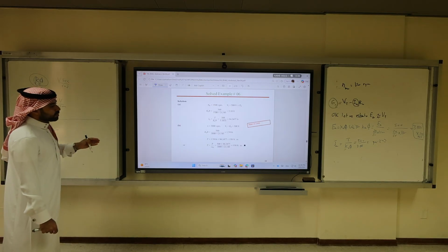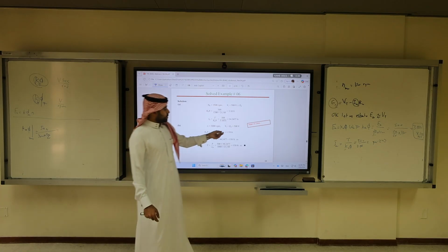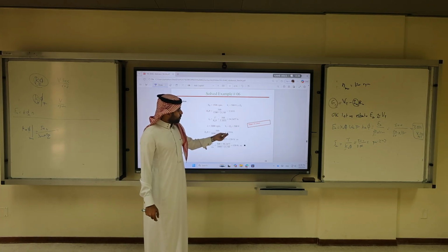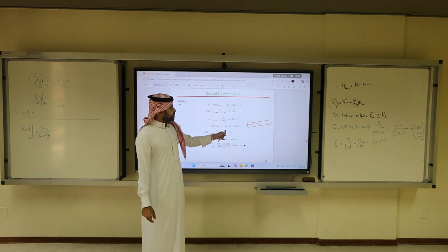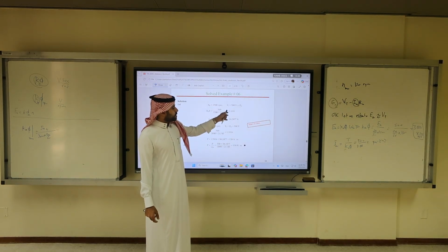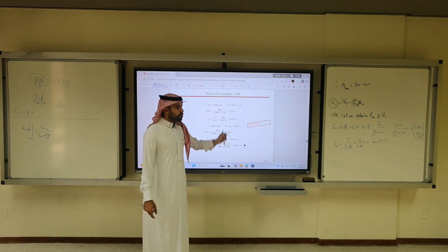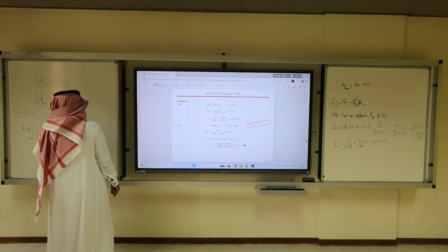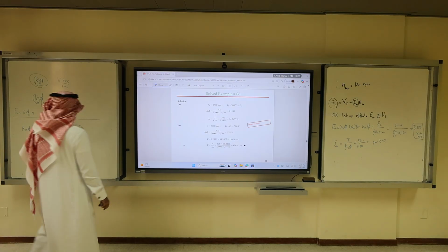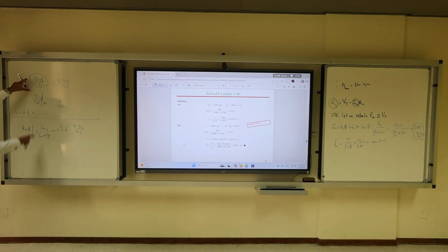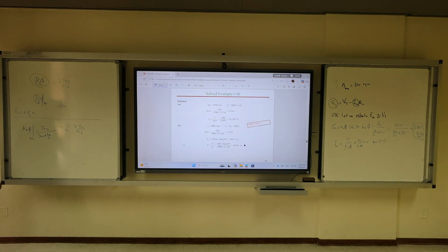So this constant will be smaller. It's field weakening, so the field becomes smaller. The field weakening constant, the Ka times flux, is now 1.6. What's the unit? Voltage times seconds over radians. Again, we're not using the RPM, we're using the one in radians. But because we changed the flux, it is now changed, okay?